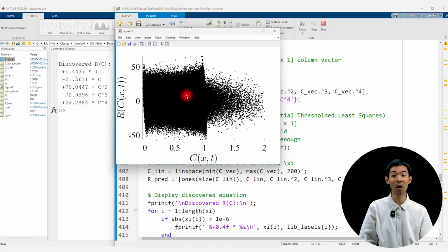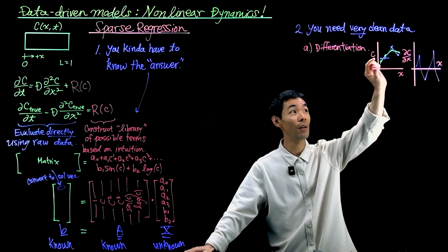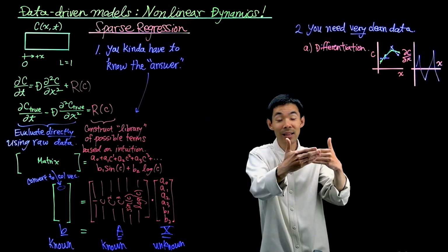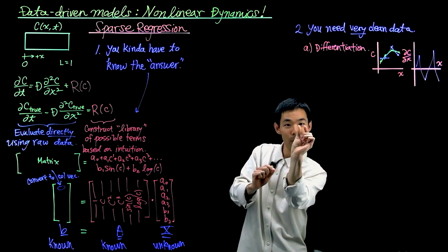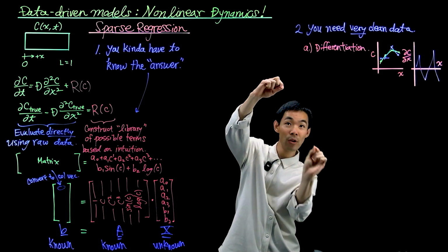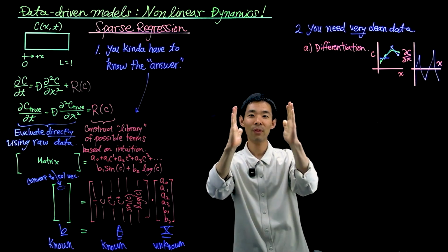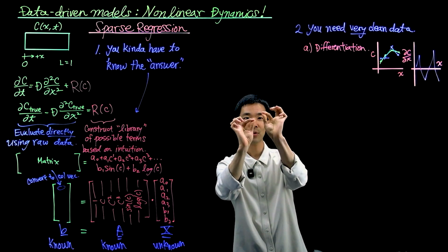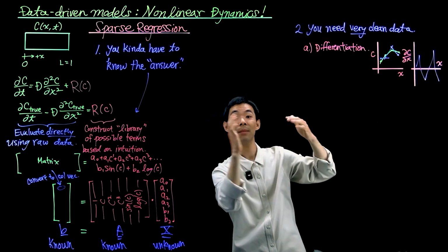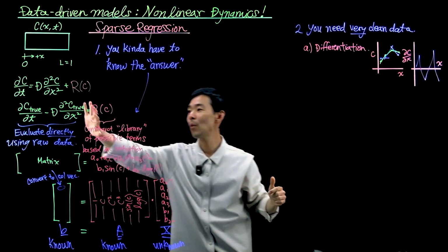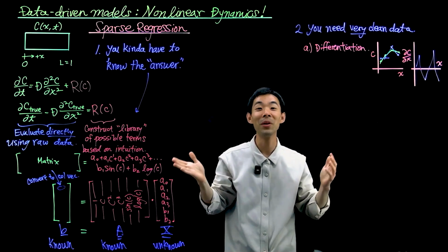And the reason why it's all over the place is because you're taking derivatives of each of those points in space and in time with noise. Therefore, you're taking differences over a small spatial region, and your derivatives are going to be super, super jagged because you have a refined mesh. Even if you move the concentration just a little bit, the slope of that error is going to be huge. Whenever you evaluate this left-hand side, you're just going to be measuring slopes of noise.